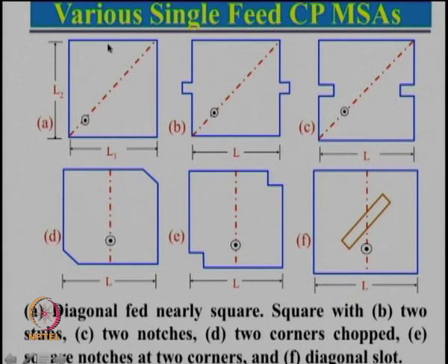So, now this will act as a resonator. Between the two resonances, this is 45 degree and this is also 45 degree. So, between the two orthogonal resonances, the phase difference will be 90 degree. That satisfies the criteria that the two orthogonal polarizations should have a 90 degree phase difference. How that particular thing is achieved can be explained.